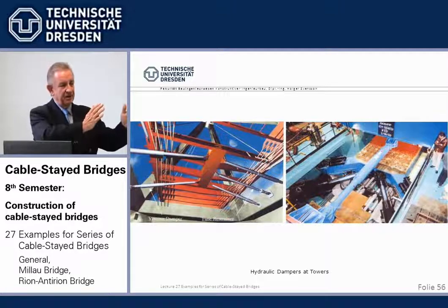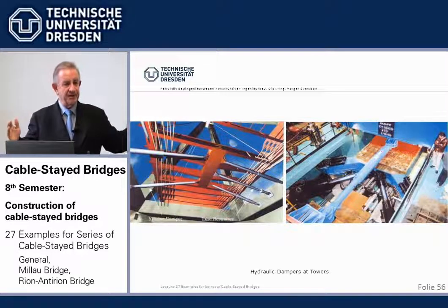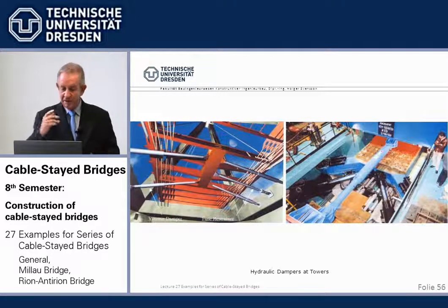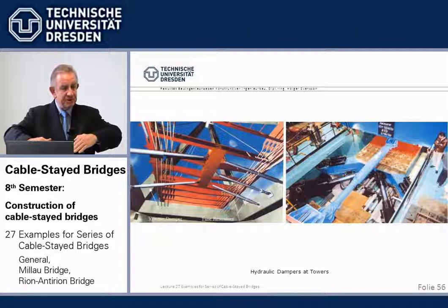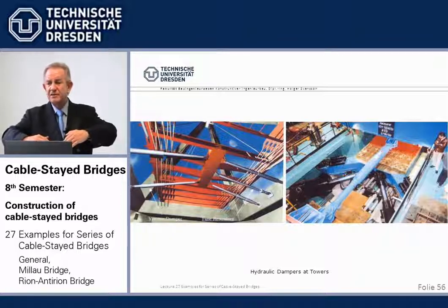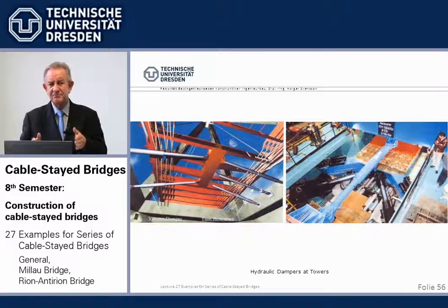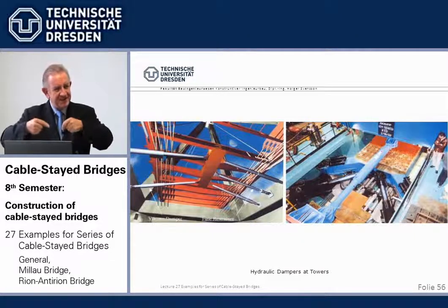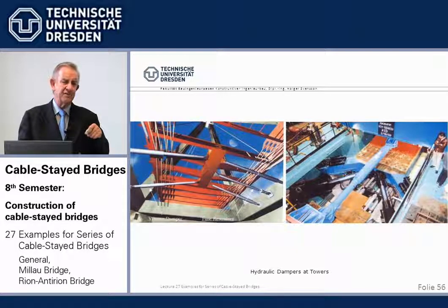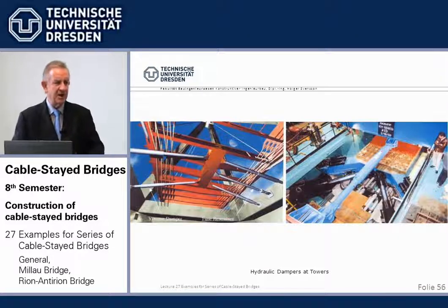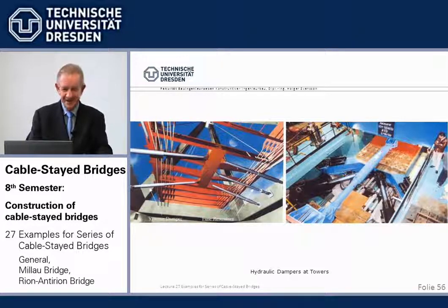Of course, we have 2-meter movement possibilities, movement joints at the end with bumpers. So in longitudinal direction, the beam is free, which gives it a low eigenfrequency, so that it doesn't respond to fast movements of earthquake when it has this long period. We did this with a desired failure joint for the Pasco-Kennewick Bridge. I told you a long time ago.